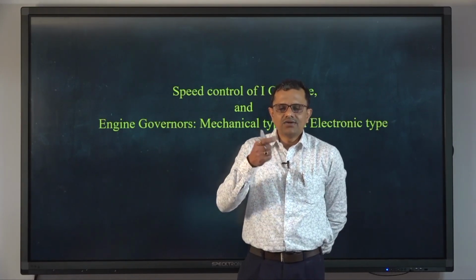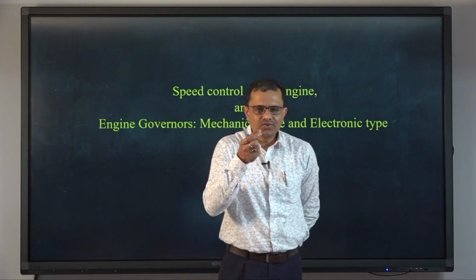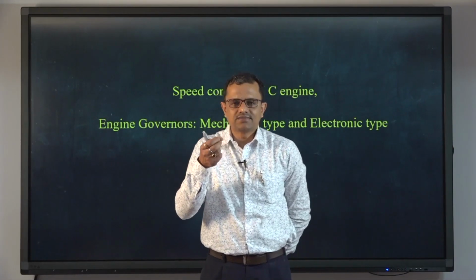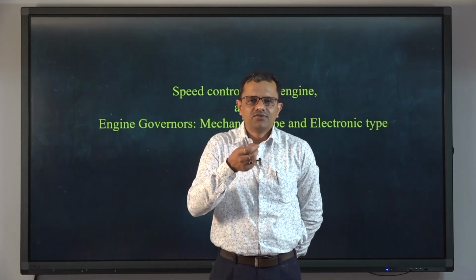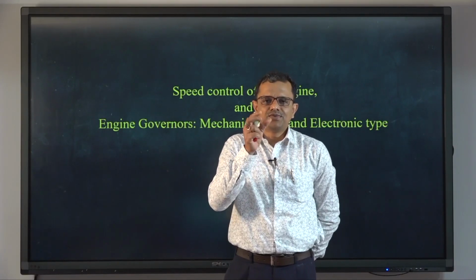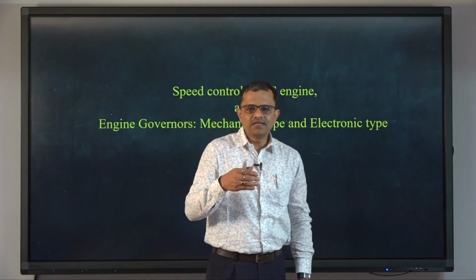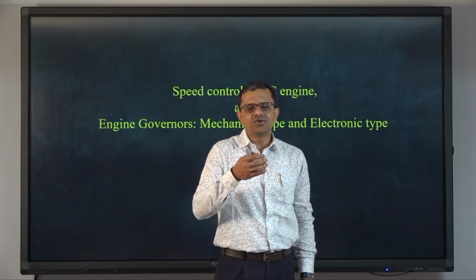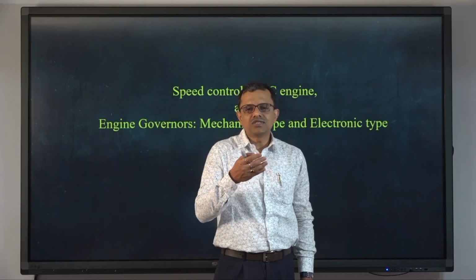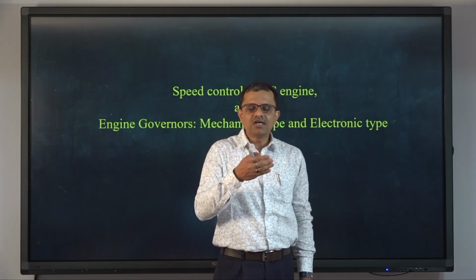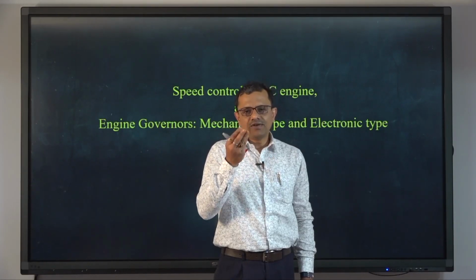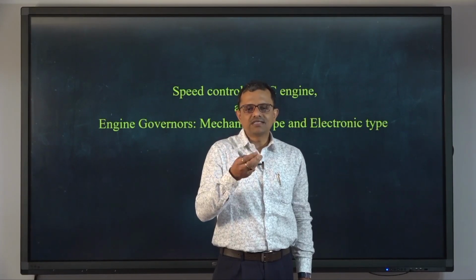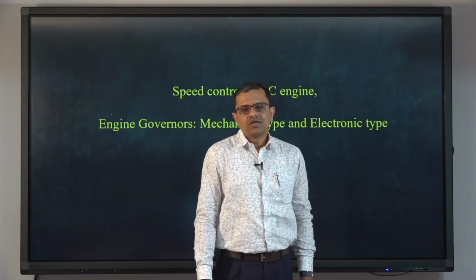So it is very important to know that sensors will be responsible to receive information about all these variables, and giving this input to the engine management system, which will control a few parameters to again bring the fuel flow rate, coolant temperature, spark timing, fuel injection timing to the baseline condition. Now, what is a baseline condition?